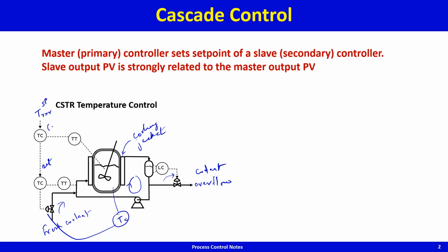So this is the reactor temperature controller, and this is the jacket temperature controller. The master reactor temperature controller sets the set point of the slave jacket temperature controller.